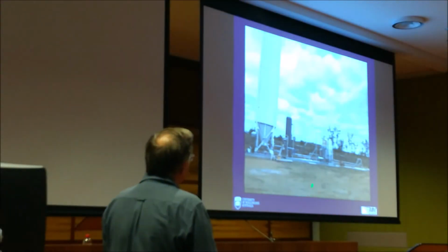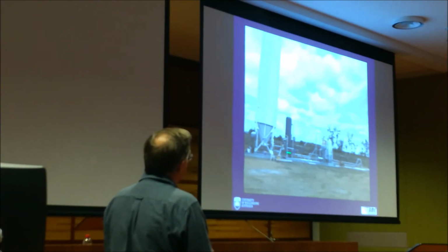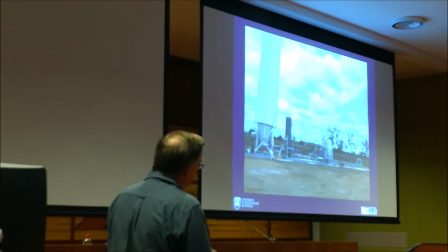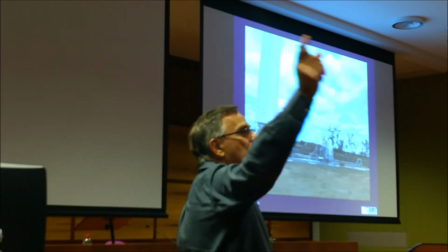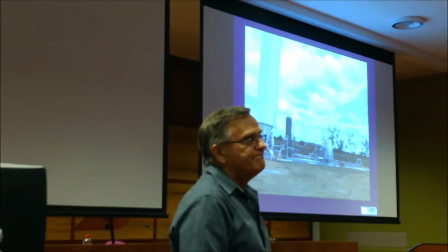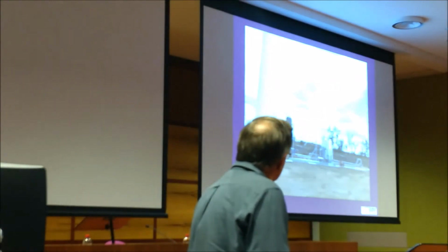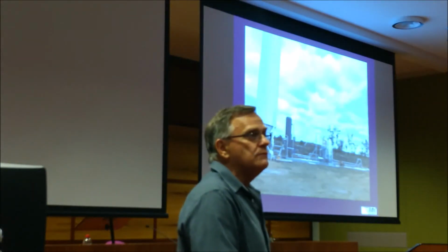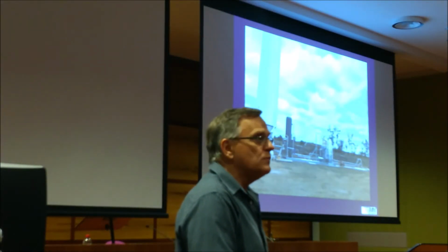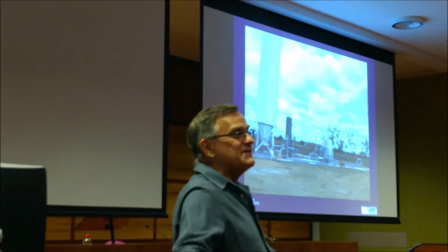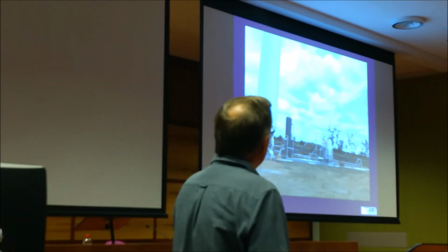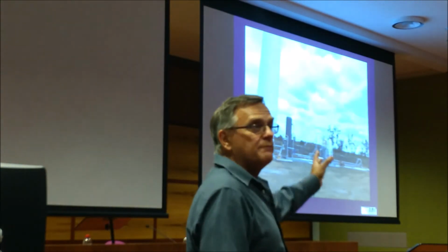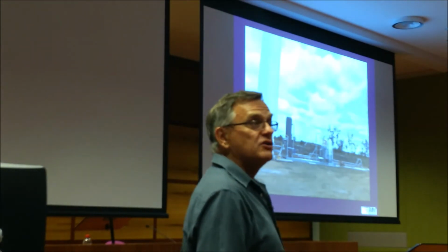And you can see here, there's the 1 cubic metre blow tanks. That's your feed silo. That's your air receiver. Your pipeline comes along here. It goes underground. It goes down to about 200 or 300 metres, and then 4 kilometres underground for an underground mine. Right, so that's it. And that system's now been operating all year. We designed it last year, did our test work in Wollongong. So our pipeline is only 100 metres long, 2.5 inch line, and based on that data, we modelled the system, scaled up the model. We developed our pneumatic conveying characteristics from our test rig.